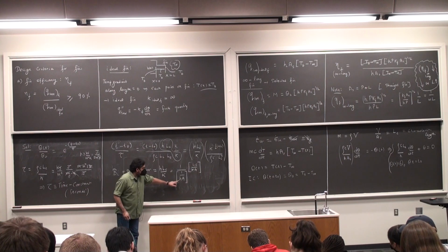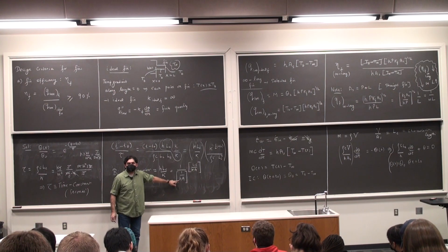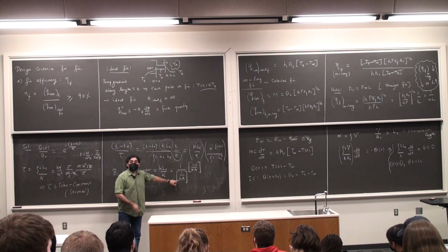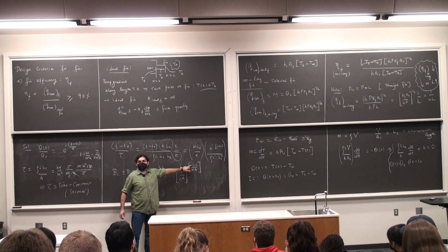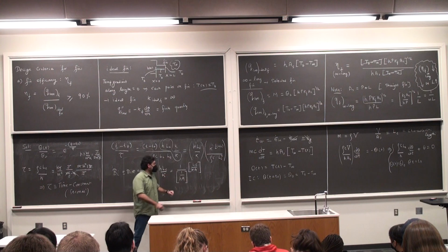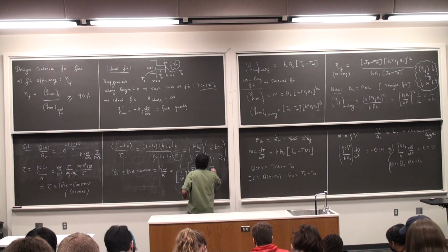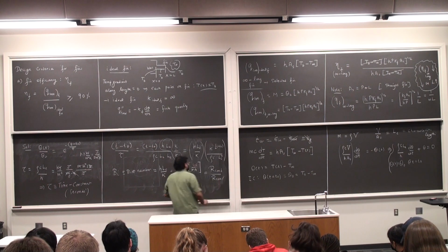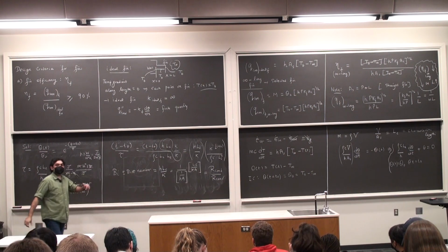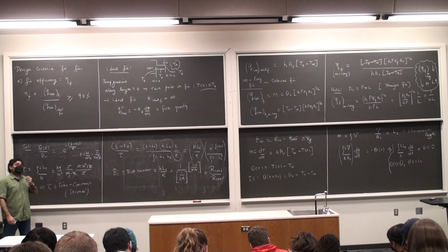Can you tell me what this first quantity is called? Convection. So this second quantity here has to be conduction, because I'm looking at thermal conductivity. So this is the ratio of the thermal resistance to conduction divided by the thermal resistance to convection.